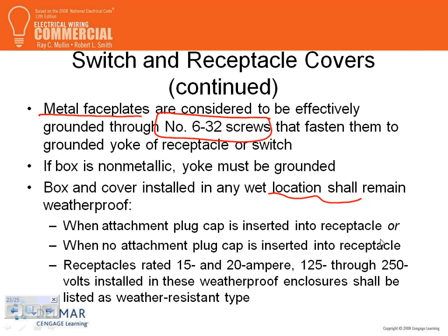You have the heavy duty cover. That bubble that you use in residential no longer applies to commercial buildings. You have to have a heavy duty one. You see them all the time that open this way, a heavy duty big metal box in 2011. So you can't get away with that plastic bubble in a commercial building anymore, from July 1st, 2011, if we adopt the code in Minnesota at that time. That's what they say, the weatherproof enclosure that you need.